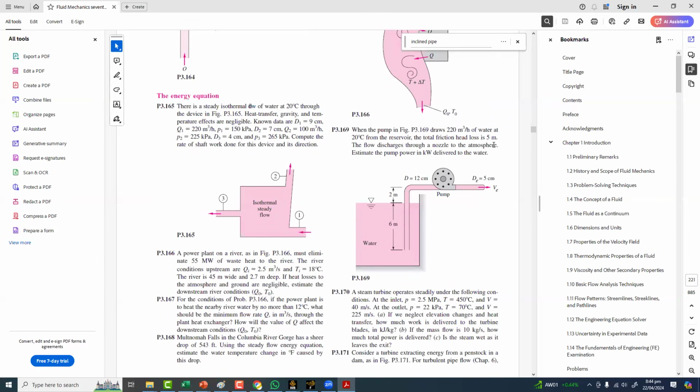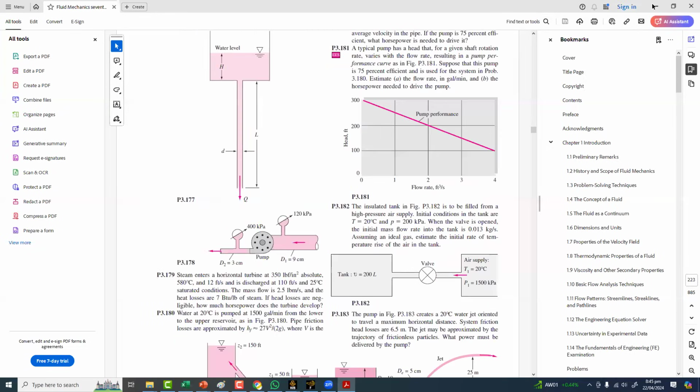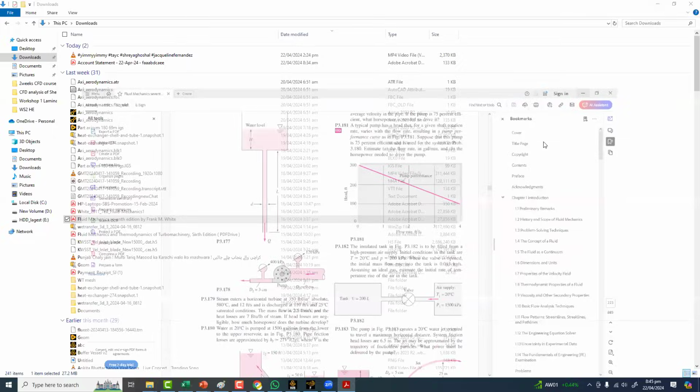So I would suggest that if you really want to learn something, make this geometry not a very difficult or complicated case, but a very simple case, and try to solve that case with the help of CFD. But try to make the problem a single fluid. Okay, if you go into two fluids, multi-phase fluid, then the problem complexity will be very, very high. So at this point, I would suggest going with a problem that you can make single phase, single fluid, or maybe you can simplify it to single phase. So you should be able to solve this problem very easily, I think.